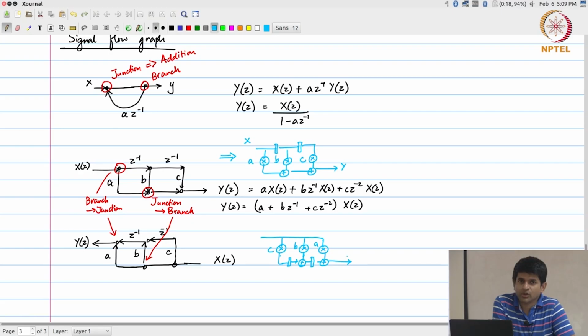is there anything that you can notice over here that tells you whether one is better than the other in some way? What's the primary difference that you can make out between both of these? So the shifting, the order in which you do the shifting, whether it's before the multiplication or after the multiplication, or rather, what are you multiplying? Are you multiplying the results of the shift and then adding, or are you multiplying something and then adding and shifting in some other strange way, right?